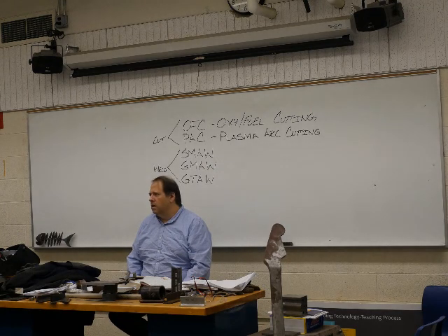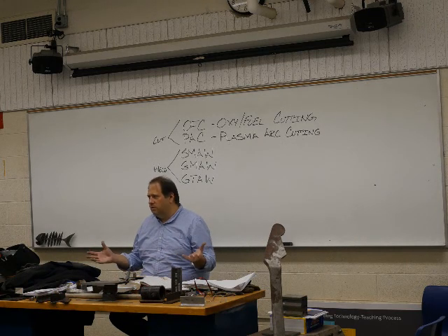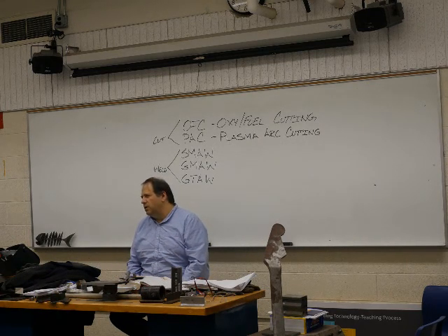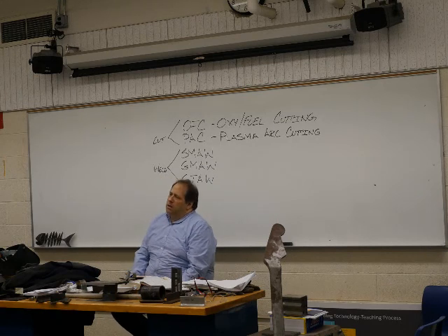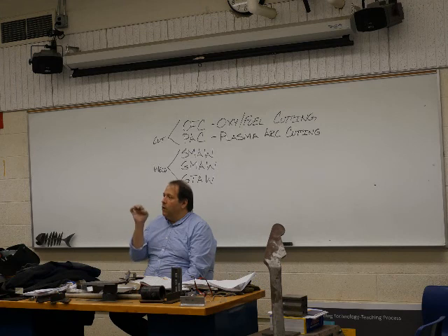You're saying the plasma can't go past 3/4, or it can? It can, and you've got to really get a pretty beefy system. Most of your just normal systems that you buy, that's about as thick. So is it the heat factor that allows you to get so detailed with the plasma cutting? The heat and the focus of the arc. So the tipping is also as well.